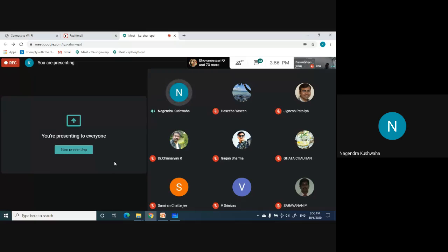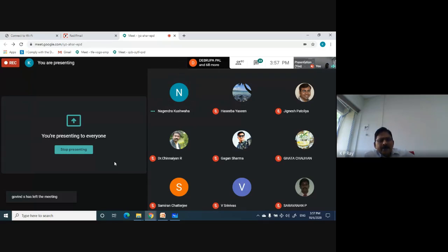Sir, the next question is whether PIFA is required for IoT. The PIFA antenna, known as the planar inverted-F antenna, is nothing but a loaded monopole antenna. And people use the PIFA antenna for IoT wherever you have a radiation pattern corresponding to that loaded monopole antenna. You can use the PIFA antenna for IoT.